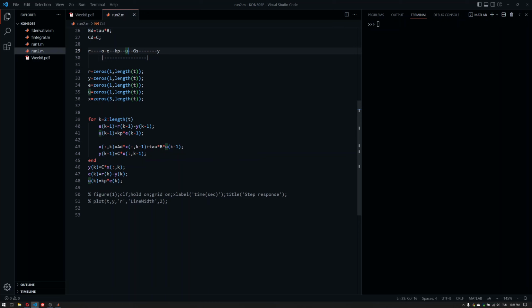But the system has one sample to react to it because we are using the zero order hold method. We assume that during the time differences, everything is stable, even though in continuous time that's not possible. But we keep it a glimpse of time, so that's not that big of a deal. So we then end up in the next sample, and then the next sample again starts from here. Our k equals 1, or r1 minus y1, e1, then u1, and then y2, and then r2 minus y2, etc., etc. So this is the way we are basically imagining stuff happens in terms of time.